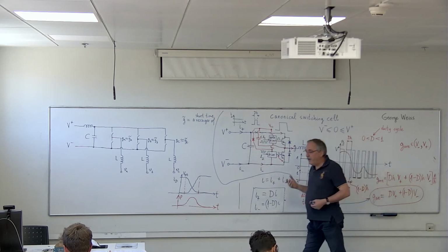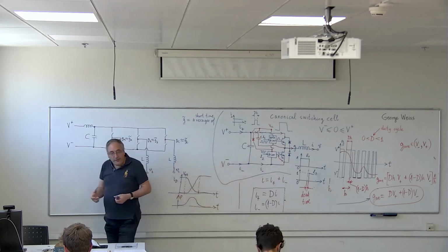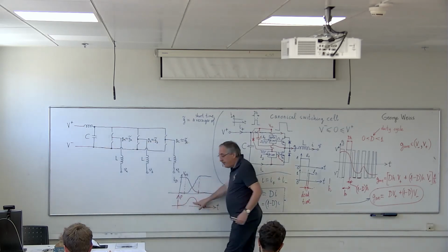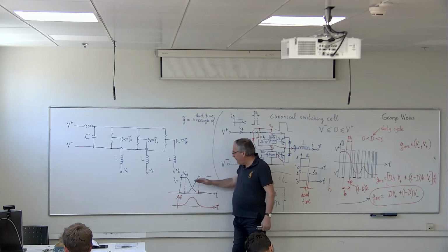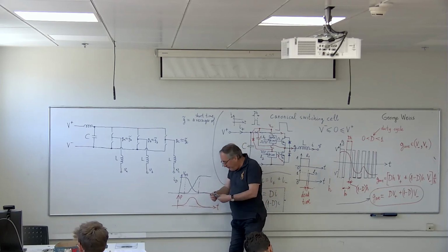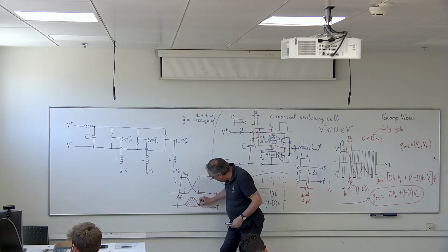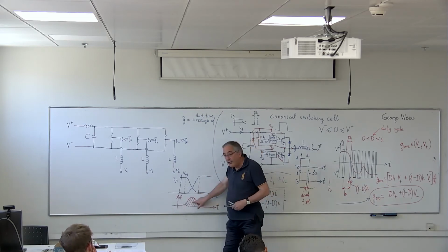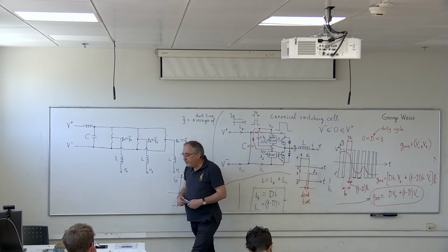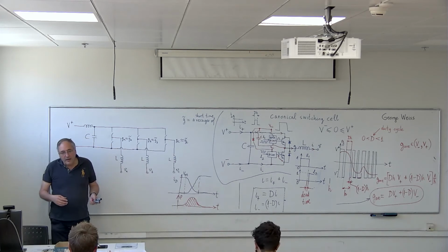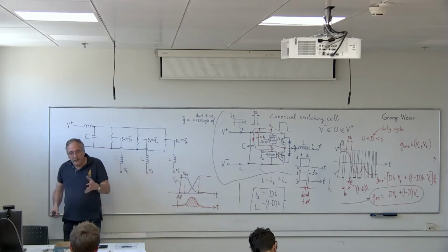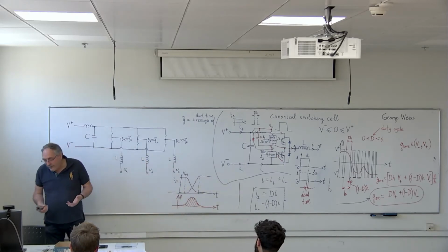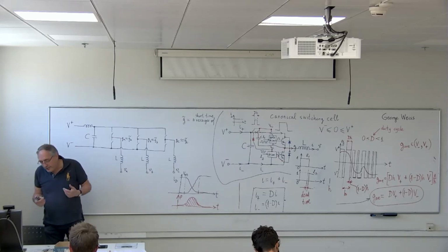But there is a cost of going to very high frequency. The cost is precisely these losses in power, because this loss is a given. If the voltage is given and the current is given, then each switching costs you a certain amount of energy. This integral of the power is the amount of energy that it costs you one switching. And if the switching frequency is high or low, the amount of energy you waste in one switching is more or less the same. So if you switch very fast, then you waste a lot of energy into the switching.